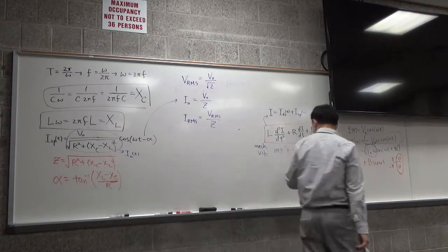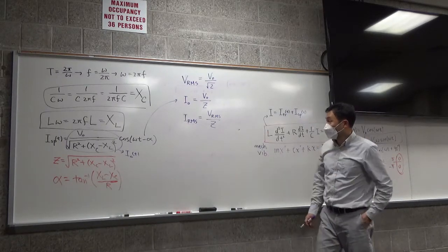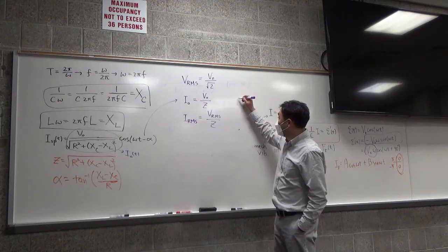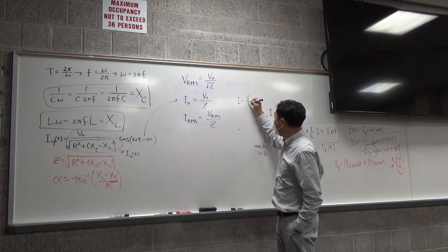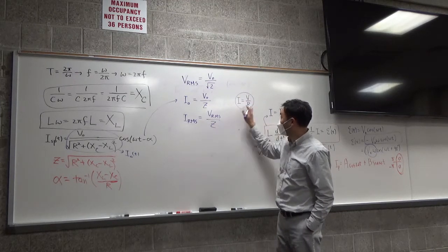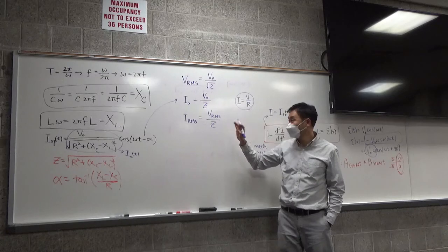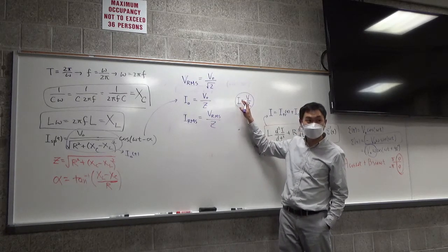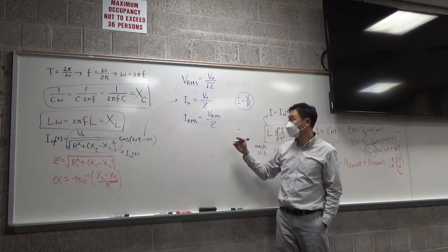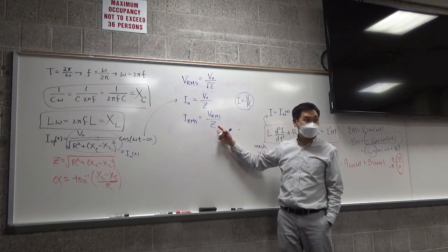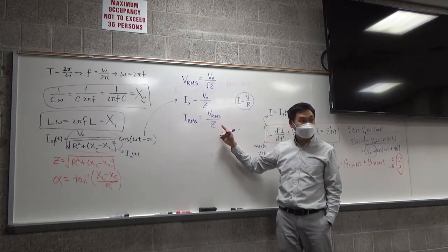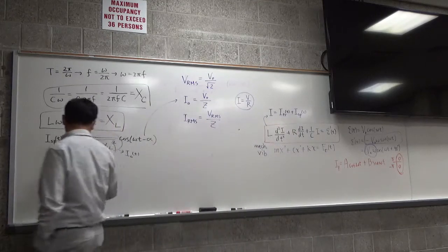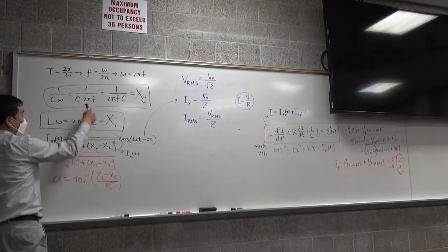And then if you compare this with Ohm's law, which is I equals V over R, you can see why people like the impedance, right? Because Z is working like the R. Although there's a difference, this depends on the input voltage's frequency. So Z is different for each frequency. See, in the formula, XC and XL both depend on the input frequency.